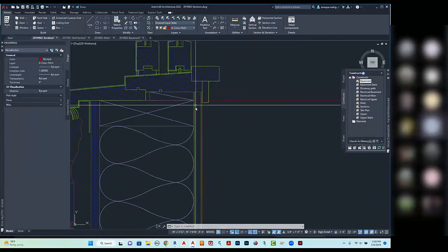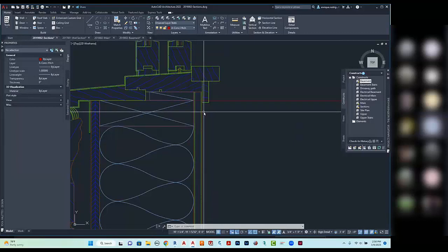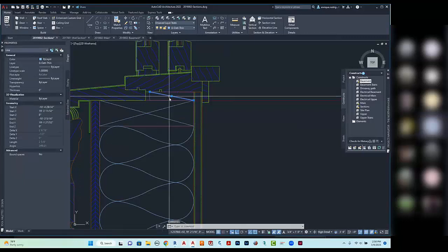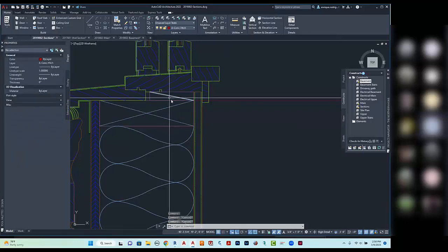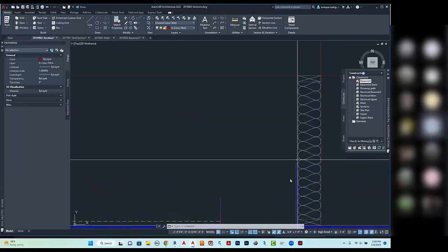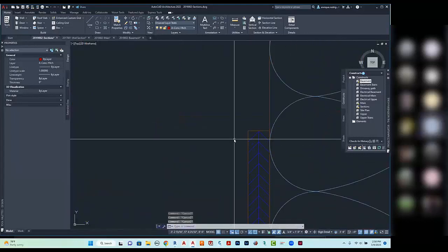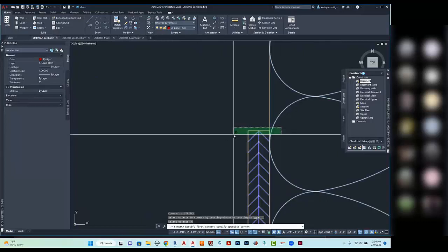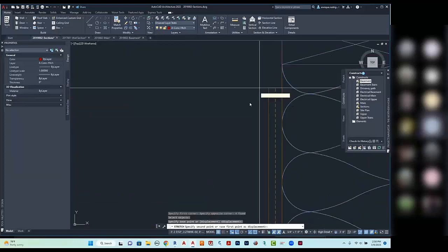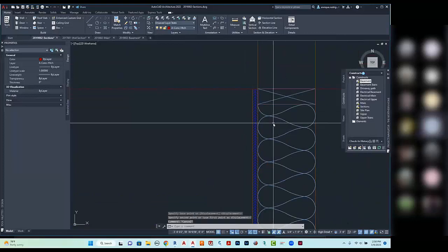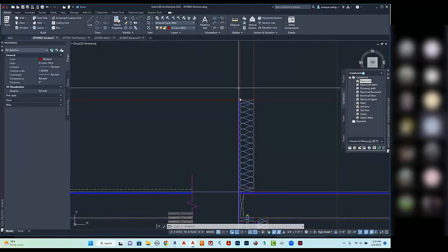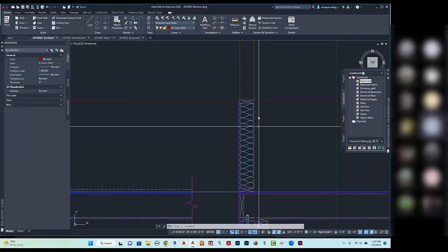We're going to do the same thing with this guy, with the 1/2-inch gypsum drywall, but we're going to stretch it up a little bit more to this point right in here. This is shim that allows you to straighten the window out. So let's go ahead and stretch this plywood from here, all the way up to where we had that line located right in there. After we put the window in, we're going to go ahead and do the drywall.